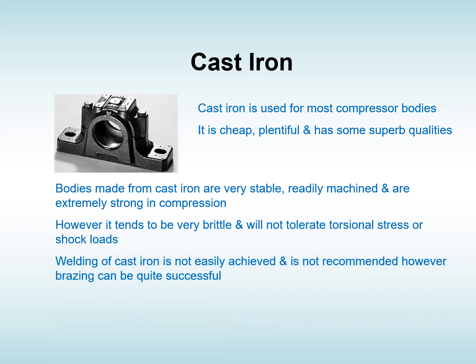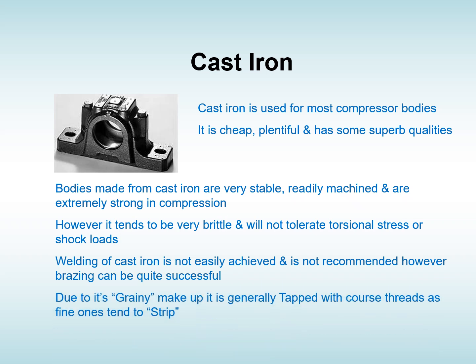Welding of cast iron is not easily achieved. It can be done, but it's not recommended. However, brazing can be quite successful. Due to the grainy makeup of it, it is generally tapped with coarse threads, as fine ones tend to strip or pull out.